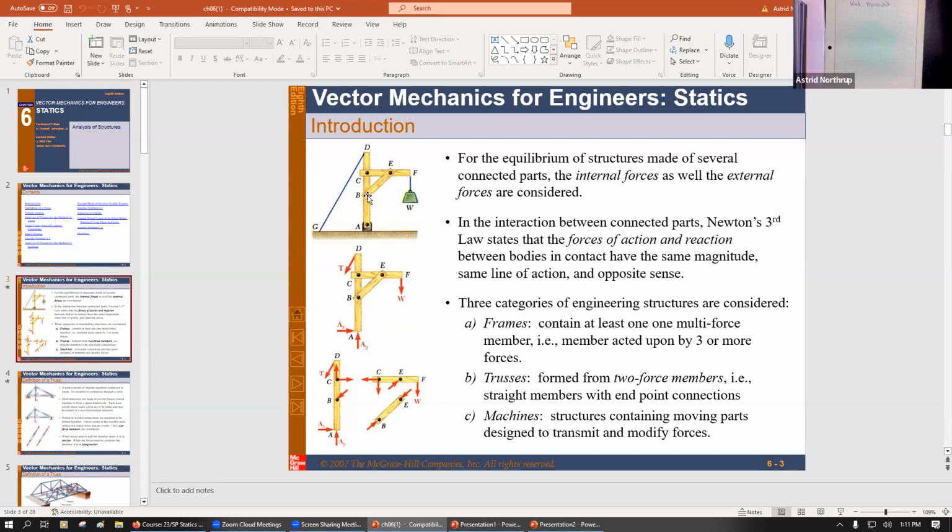But if you look at that structure, if we eliminated the structural member BE, what would actually happen, do you think? In other words, if we eliminate this cross-structural support, and we just have this borne right here, all of the force from the weight is being borne on this fastener, point C, and it's quite likely that if the weight is heavy enough, that CF would actually collapse and fold into the upright support. We have no way of knowing that without doing the math. However, when we put in a cross-structural support like this, the reason is that we want to have the load borne in a different way.